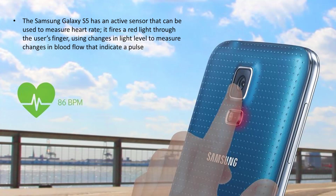A good example of an active sensor is the heart rate sensor in smartphones, where you put your finger on it, and the sensor will emit a light and measure the changes in blood flow that indicate pulse. So you're measuring the changes in the light level by injecting a light and observing the changes of the environment.